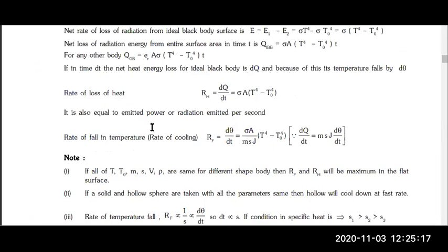Okay, now what kind of question can be asked in this? If I'm having two different temperatures and I want to find how much power is radiated from one temperature to the other, you just have to find the difference. The rate of heat transfer is nothing but the amount radiated at temperature T1 minus the amount radiated at temperature T2. Tell me yes or no, right?